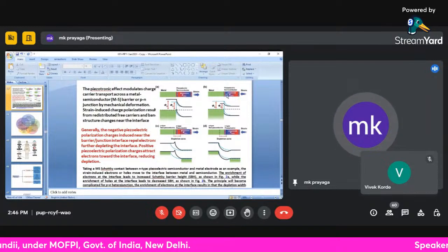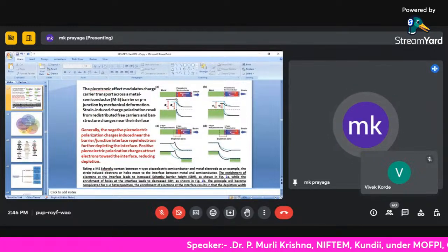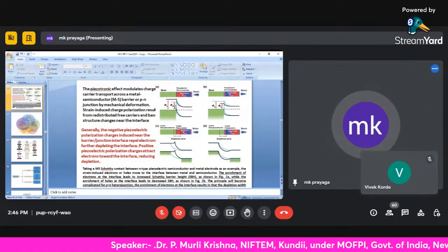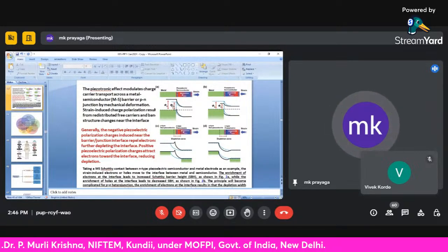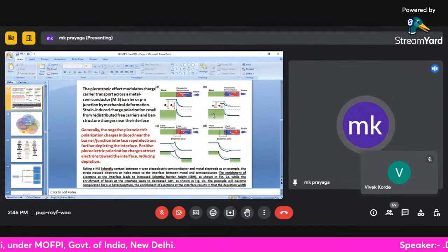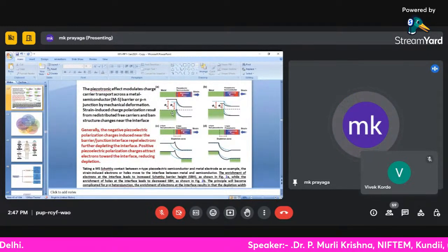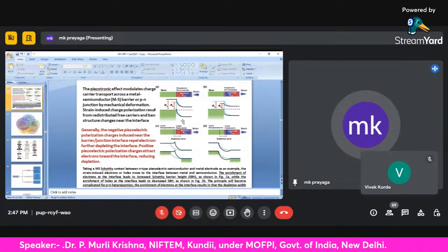Here it is negative, here it is positive. Based on this positive and negative, the electron densities from the metal tune this junction barrier, that means the Schottky barrier effects. The height will change, so that will create the transition of electrons from one location to another. And of course, a similar phenomenon you will find even in the field effect transistor also.